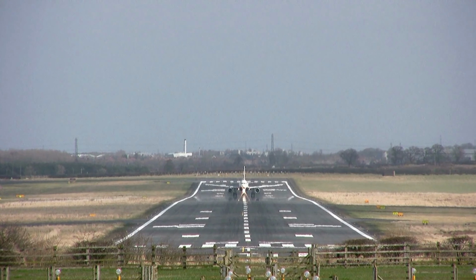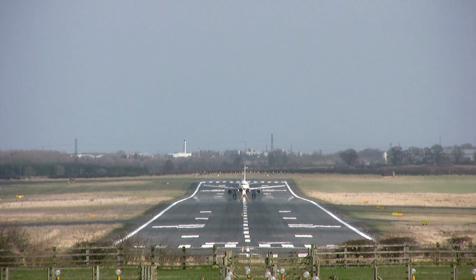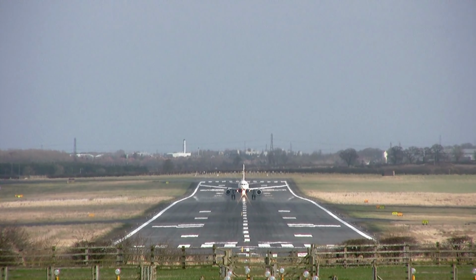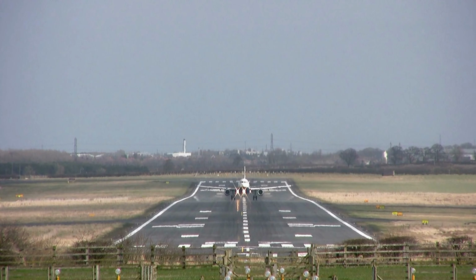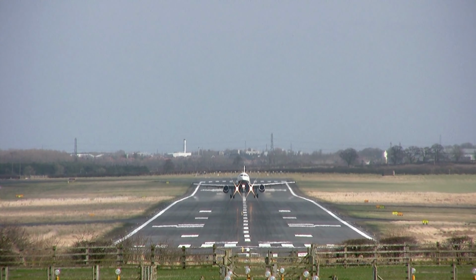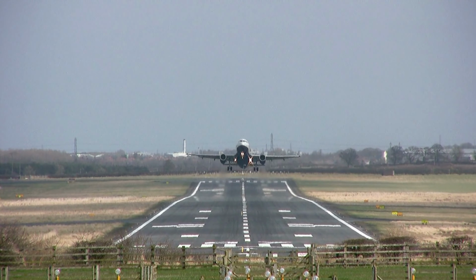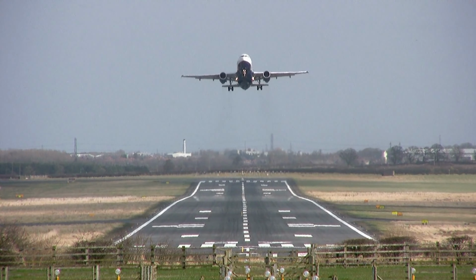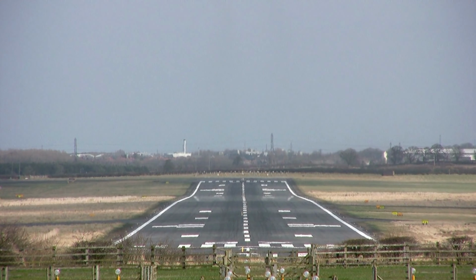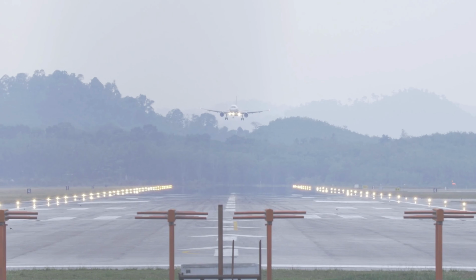While ATC does space departures and arrivals to allow time for the wake to dissipate, the final responsibility for wake avoidance lies with the pilot. The most reliable way of avoiding wake turbulence is waiting till it dissipates. But for operations at busy airports or at uncontrolled airfields, pilots can use these guidelines for minimizing the chances of a wake encounter. Avoiding vortices in flight.